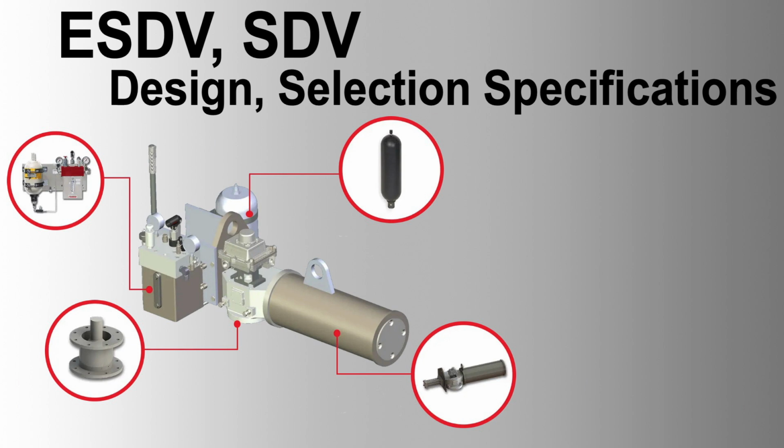Nameplate details: equipment must have a primary nameplate of 316 stainless steel, containing information such as item tag number, manufacturer's name, model type number, serial number, actuator type and speed, pressure rating, valve size, material, flange rating, IP rating, hazardous area classification, action on air supply signal failure, and NACE requirements. Packaging: supplier is responsible for preparation for shipment, including packing, marking, and transportation, as specified in the commercial section of the ITB.